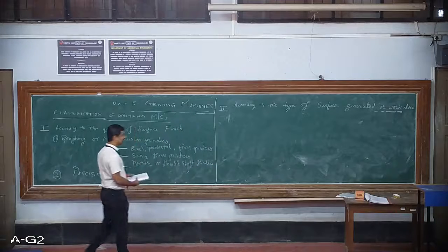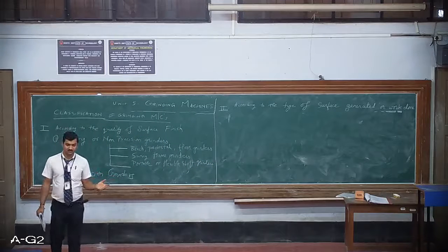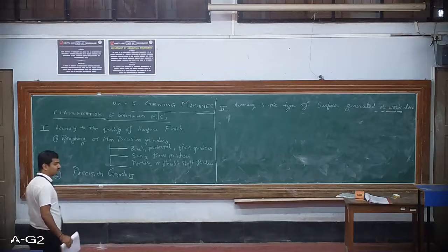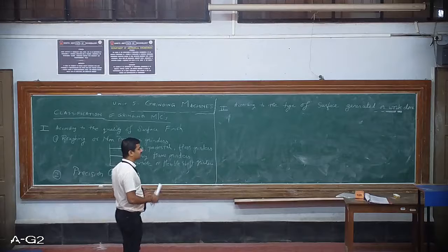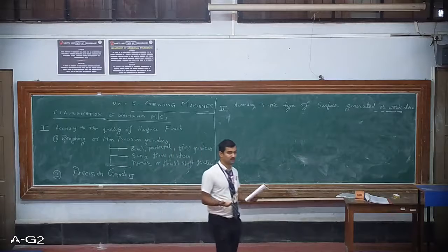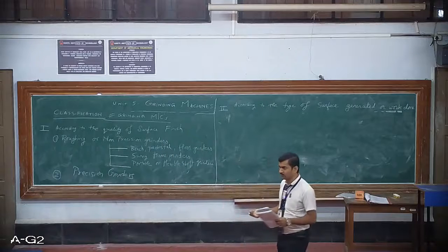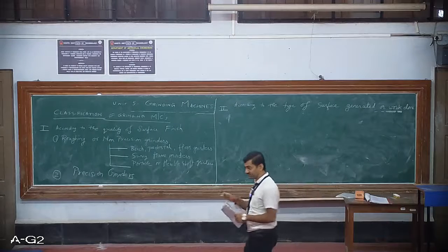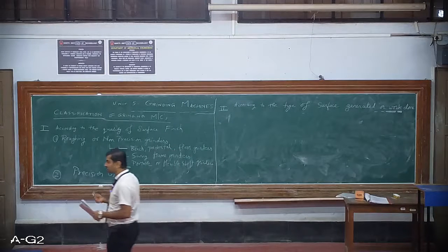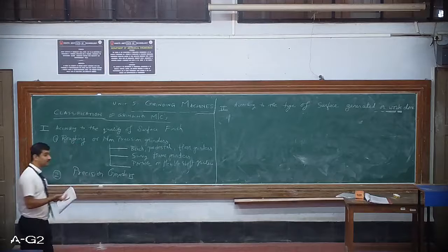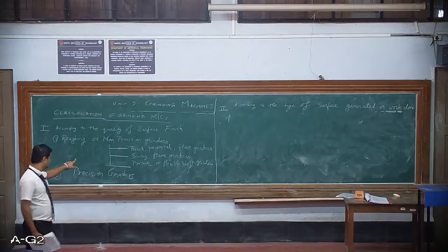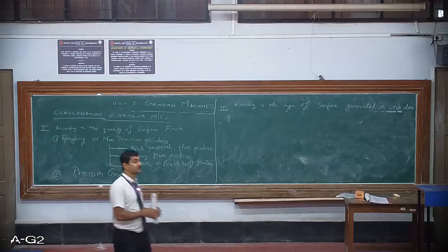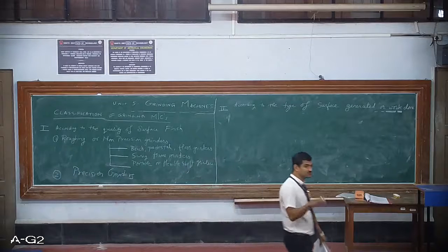Now, the naming itself makes us understand that it is very specific to the quality of surface finish. You might have observed sometimes the laymen or the working people at construction sites, they use a hand grinder. They just tilt and twist and keep grinding the surface, right? Polishing or grinding. Generally, they have flexible grinders. So the words bench, pedestal or floor grinder refer to the grinder being fixed onto the bench.